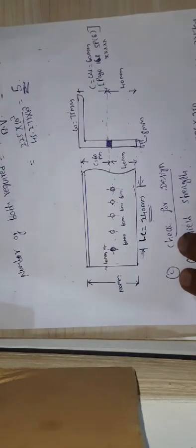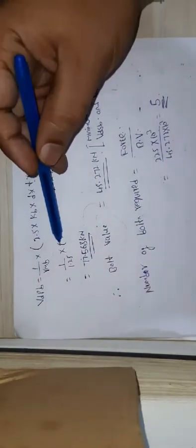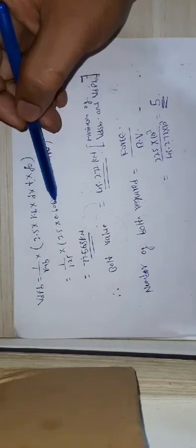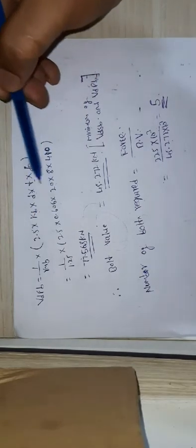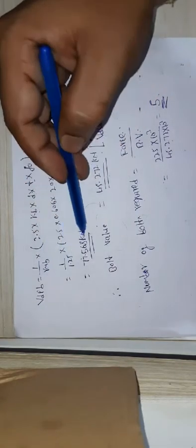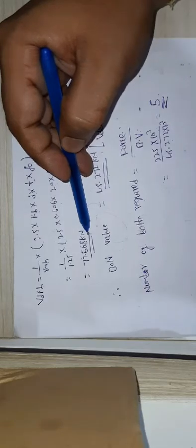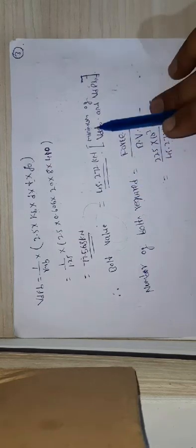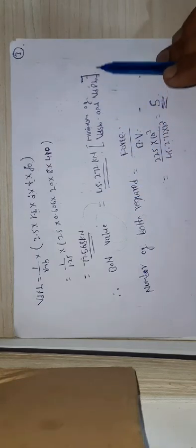Guys, please, how to calculate KB is there in page number 75. Please go through that. By using this KB value, I can easily calculate the strength of the bolts in bearing. Substitute here the least value 0.606. D is the diameter of the bolt, T is the thickness, and Fu is 420. So I got VDPB equals 77.568.